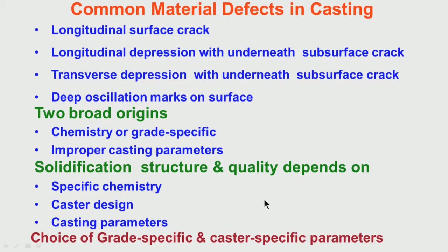So, mold shrinkage means mold taper has to be more. That means the distance between the two plates of the mold at the bottom of the mold is slightly less compared to the top of the mold.